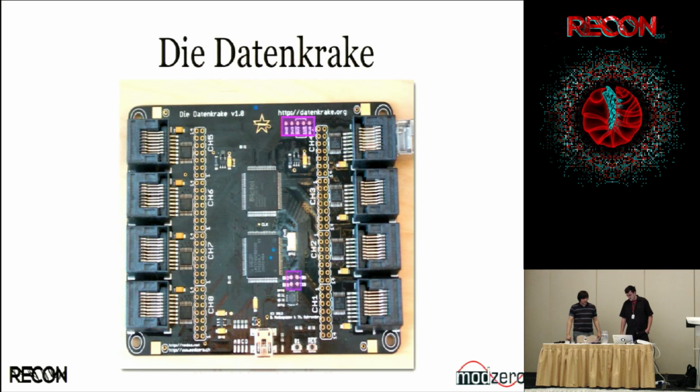But we also have these test pads, which are awesome. Don't ask me where I saw this first, but I'm giving you a free pro tip. If you design a new board, what you should do is put ground planes on the corners. Now you can take your oscilloscope probe and just clip the crocodile clip right there, so it's not flying around all over the board, irritating you, getting in the way and grounding something out, and then you have chips exploding and whatnot. So, safety first.